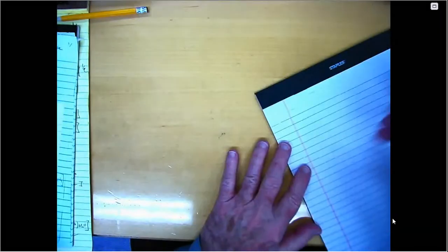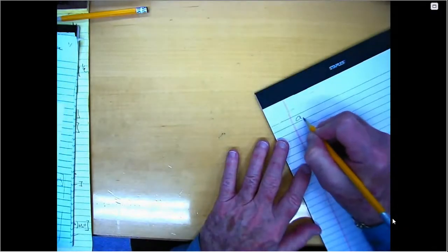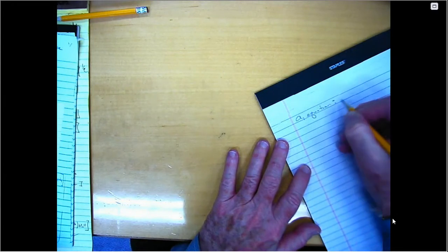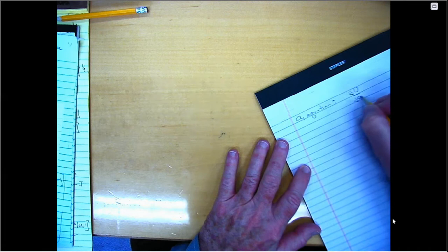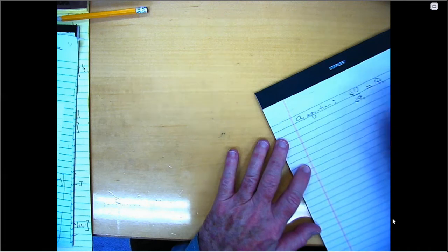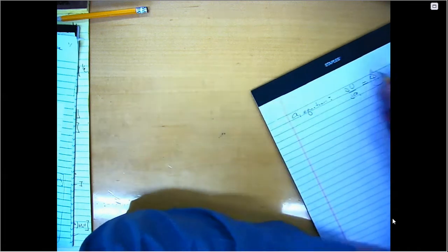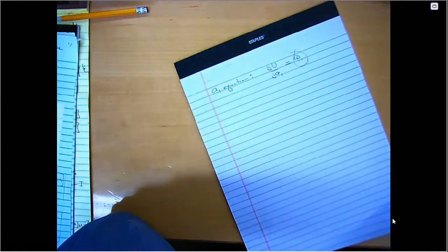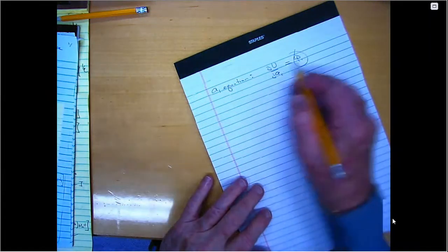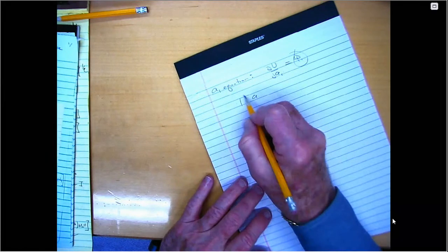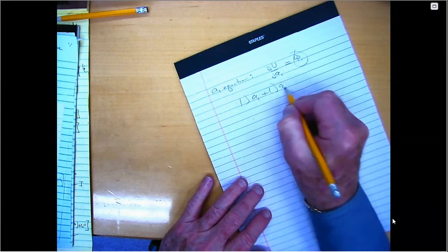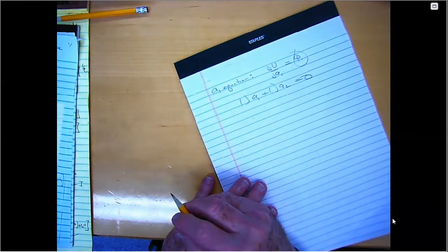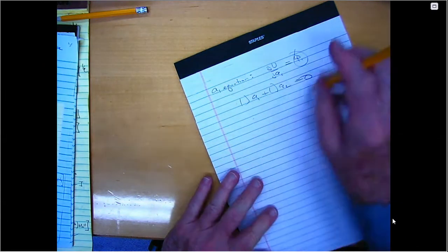You're going to end up with, let's say, I'll call it the A1 equation. What do I mean by the A1 equation? Just the one that comes from dU/dA1 equals capital Q1, right? And capital Q1 by definition is the coefficient of del A1 that appears in the virtual work. Okay. In general, that equation will be some coefficient times A1 plus some other coefficient times A2 equals 0. Okay? But it may be, or no, it won't be 0. Sorry about that.